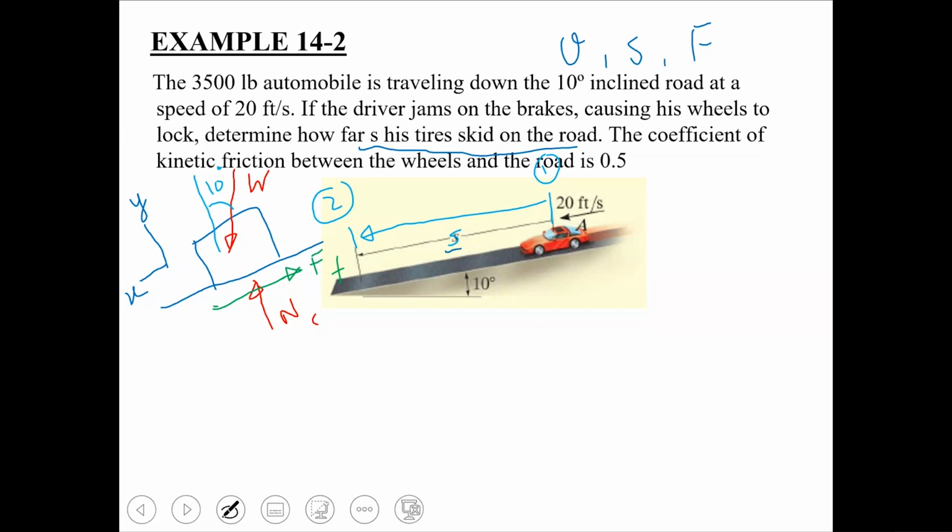Here these two positions are shown to you as position 1 and position 2. इसके मुकाबले में अगर हम equation of motion की बात करें तो since equation of motion is a vector equation, so वो equation आप हमेशा किसी ना किसी axis के along कोई coordinate system में apply करते हैं. इसके मुकाबले में work energy चूंकि scalar quantities हैं, so it is going to be applied between two positions rather than along some axis. Okay, so we are going to apply the principle of work and energy on this car between position 1 and position 2.